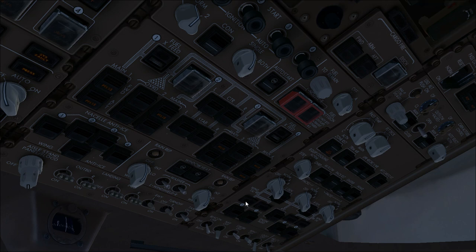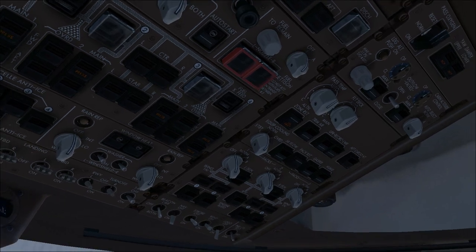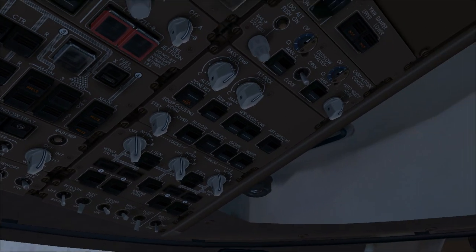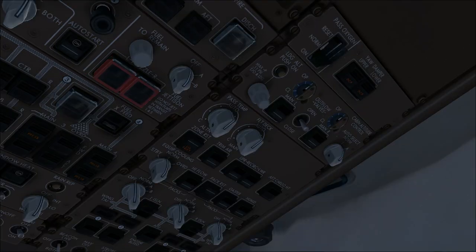The next part is on the last column of the 747 overhead panel. As you can see, we have the passenger oxygen guard switch, must be guard closed, and do not open it because if you move it to on, it will release the oxygen masks in the cabin, and the oxygen pressure will decrease slowly until it reaches zero, and you will have some indication on the upper DU for that.